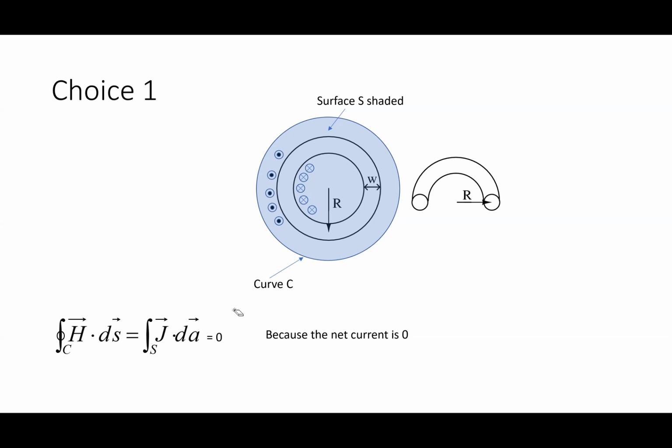So it says here, I put 5 turns on this thing, right? So I have 5 times I coming up. And what do I have on the other side of the inductor? Negative 5I, right? Because directionally, I got 5I coming out, negative 5I going in. So I got 0 net current going in. So how much field is going to be around that edge of that surface? 0. All right. So there is no field out here. H equals 0 out here.